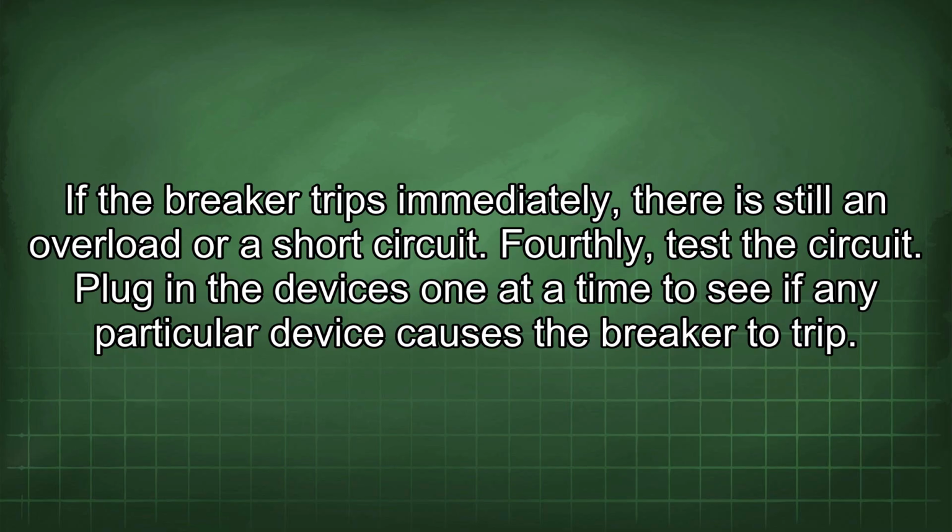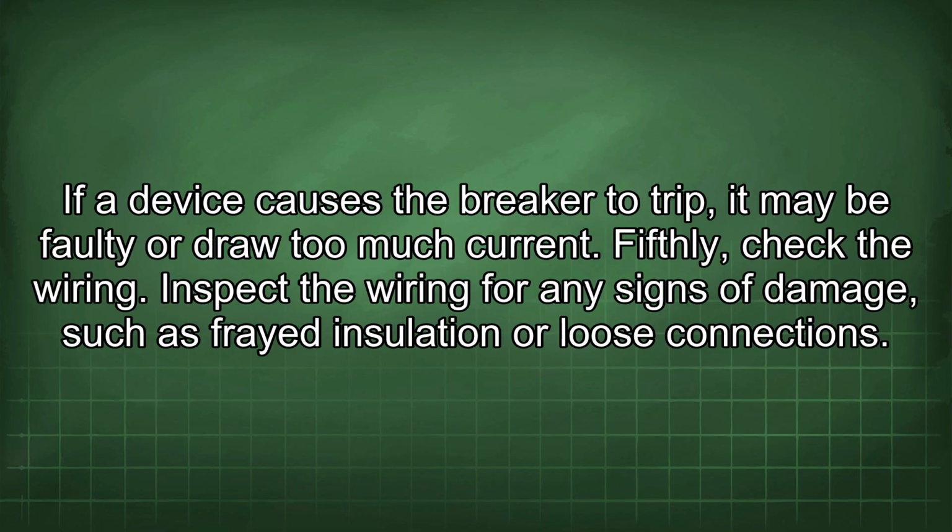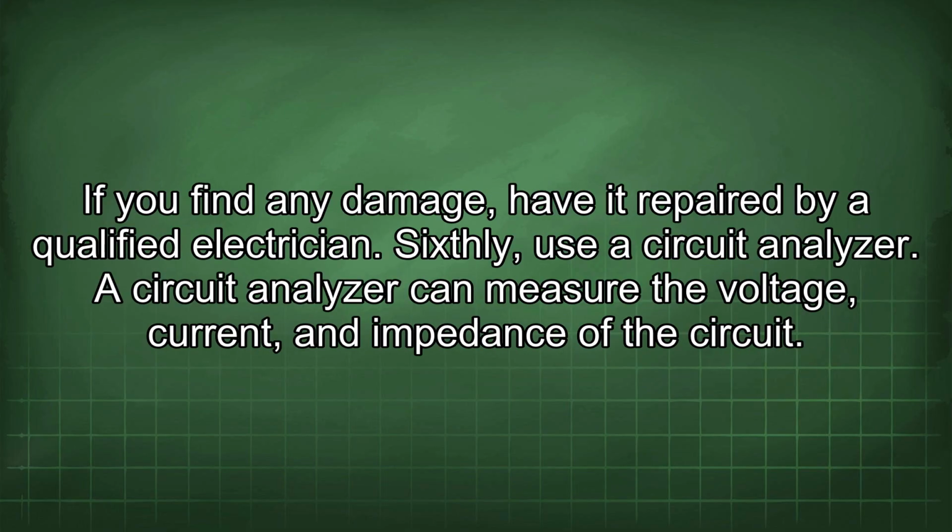Fourthly, test the circuit. Plug in the devices one at a time to see if any particular device causes the breaker to trip. If a device causes the breaker to trip, it may be faulty or draw too much current. Fifthly, check the wiring. Inspect the wiring for any signs of damage, such as frayed insulation or loose connections. If you find any damage, have it repaired by a qualified electrician.